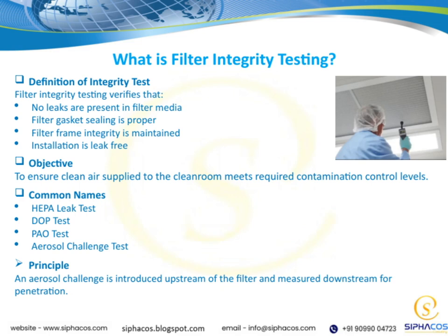Essentially, it's a way to make sure that our filters are functioning properly and that they're maintaining the high standards we need for contamination control. An integrity test checks that there are no leaks in the filter media itself, which is crucial because even small leaks can compromise the entire cleanroom environment.